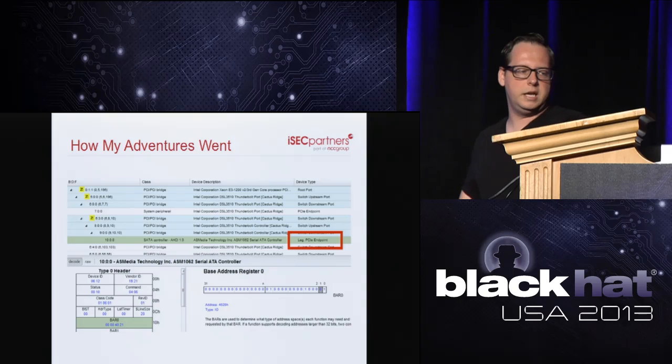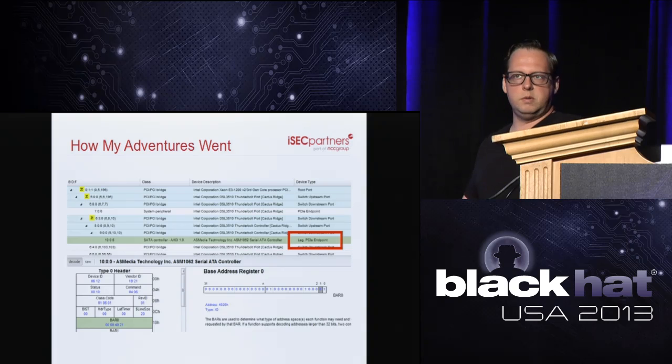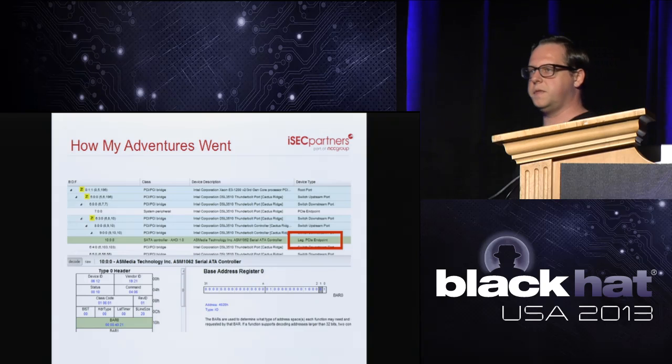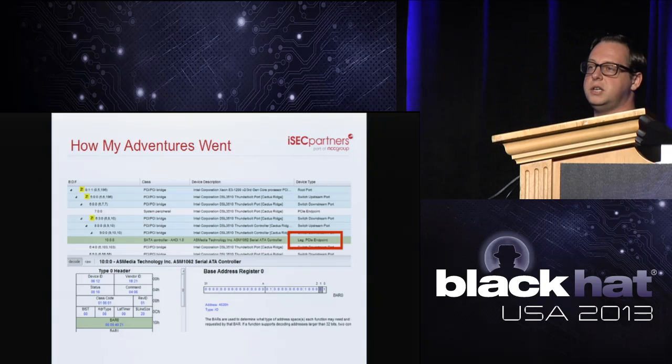So that was a pretty in-depth look at the hard drive. We've got a lot of information out. We got some great ways to pull some flashes and ROMs, and some great ways to see what's going on. We know that the ARM Cortex is orchestrating the whole thing for Thunderbolt, and the Cortex is required. We have a pretty detailed pinout of our DSL2210 chip, so we're able to take that and look at other DSL2210 chips.